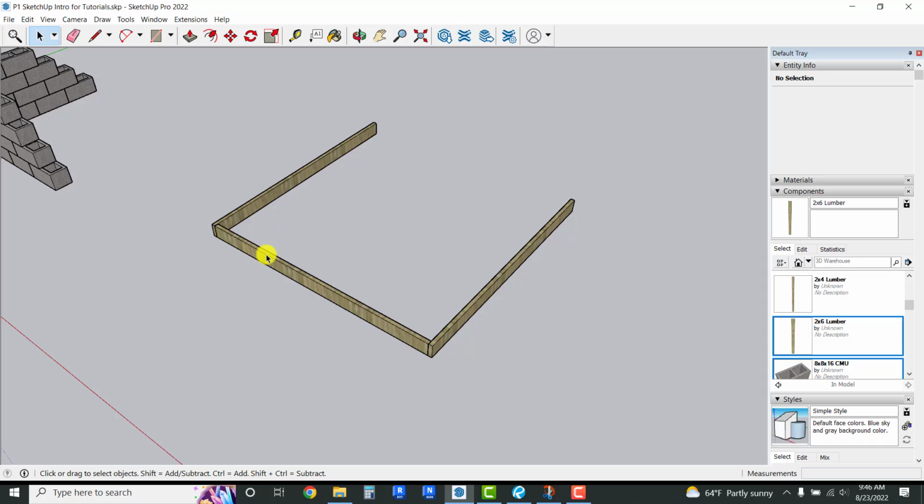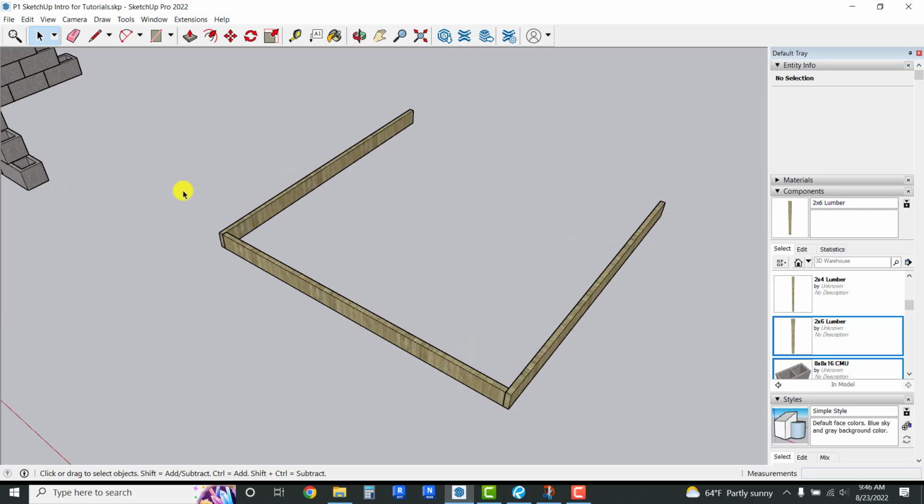Now I'm going to use this joist command, and we're going to begin the placement down, and we're going to do similar to that first row or first course of block where we did the move toggled with Control to copy and then used the X2 or X3 for an array.